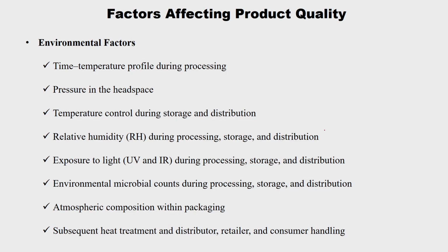So, based on this we have certain conditions, for example frozen condition. The frozen is minus 18 degrees centigrade. So, this is something under 100% relative humidity, and the second one we call a chilled condition. Alright, the storage condition, the chilled comes under like 0 to 5 degree or sometimes 8 degree as well. So, the relative humidity is also very high.